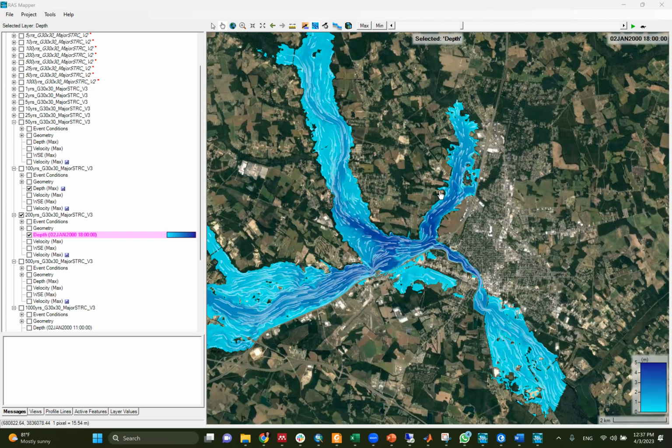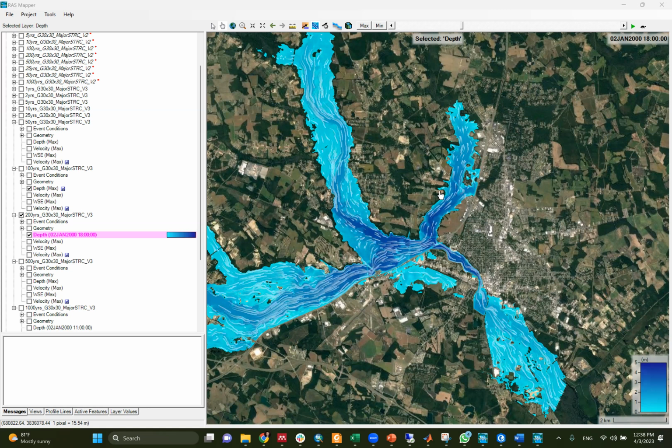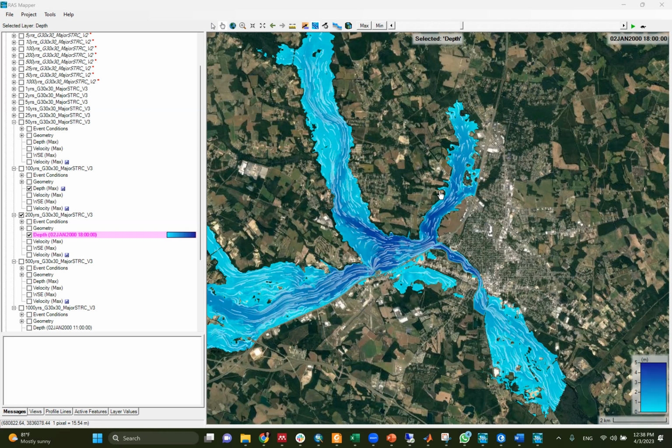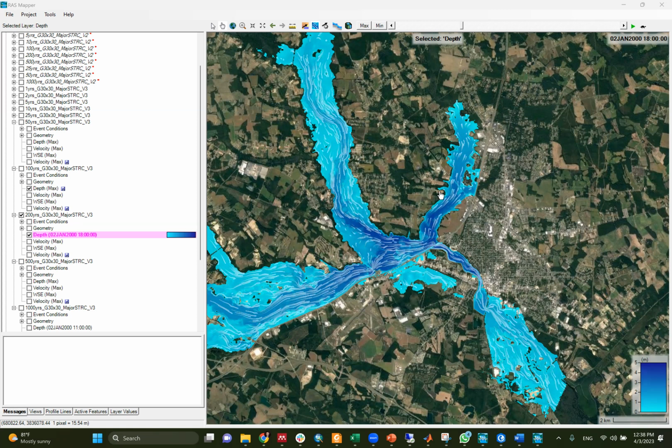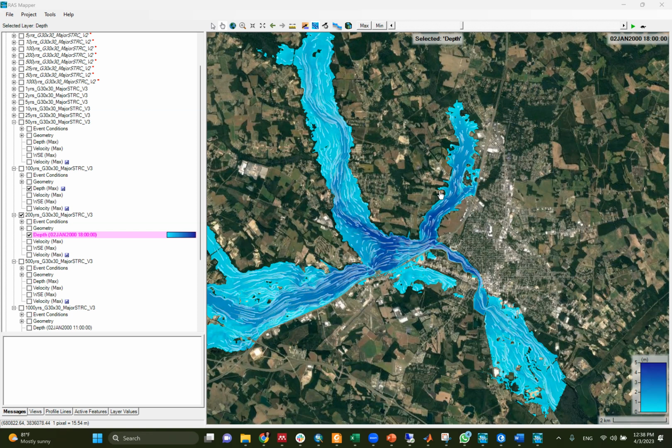Once you let HEC-RAS run 7 days after the day of the flood, say the flood started at some point, you ask HEC-RAS to run 7 days. When it runs 7 days, it keeps tracking the water until the 7 days end here. But what we want is more days, so that we can let the water go downstream and track it until it flows out of our boundary.